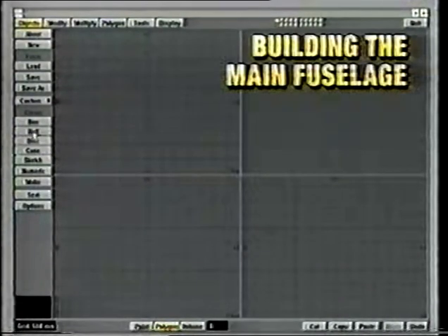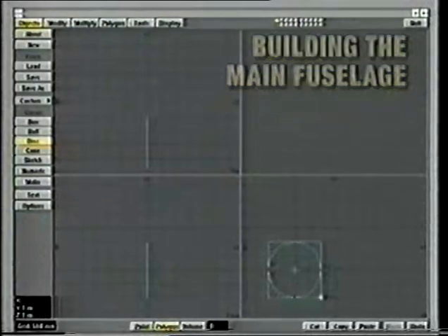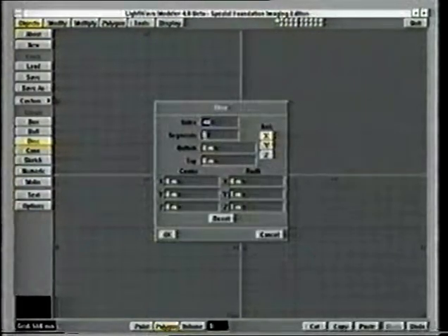To start off, the overall spaceship design is basically several cylinders, all of them cylindrically mapped. So we're going to start off by building the main fuselage. To do this, I'm going to get a disc here, pull it out, numeric, because we're going to get fairly close to it. I want to have a good 40 subdivisions. So just make that.